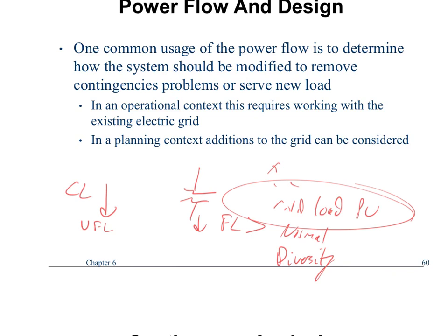Because they hadn't really anticipated what was going to happen in terms of being able to throw people on, they were super freaked out. Normally you run at 60 hertz and whatever the 1 per unit voltage is. I think they ran the generator at 63 hertz. They turned off the high-speed trip, and they ran the voltage at like 110%, because when they closed the switch, that generator just had all that load. They didn't have the ability to switch things on and off. So the generator had a tremendous amount of load and almost tripped because it dropped off in speed and voltage so quickly. That's because of inrush conditions.